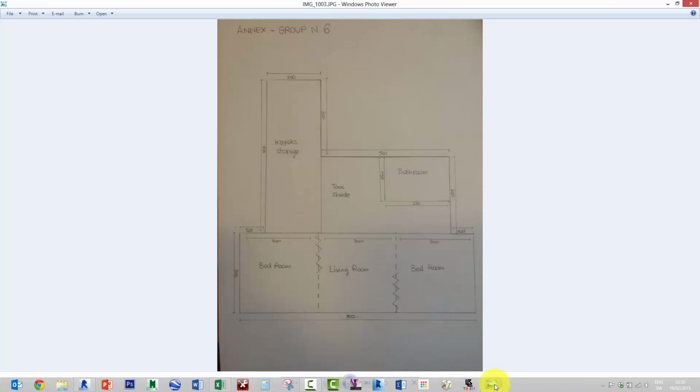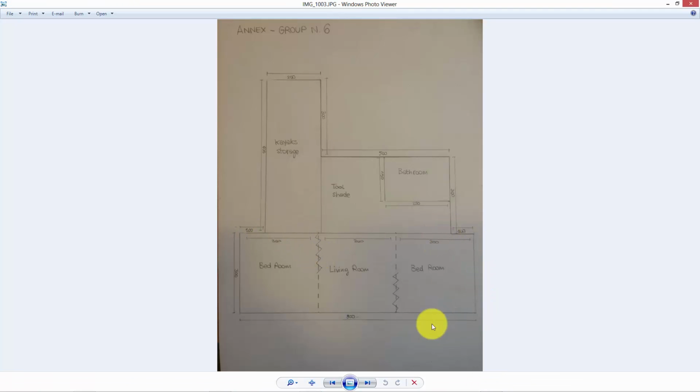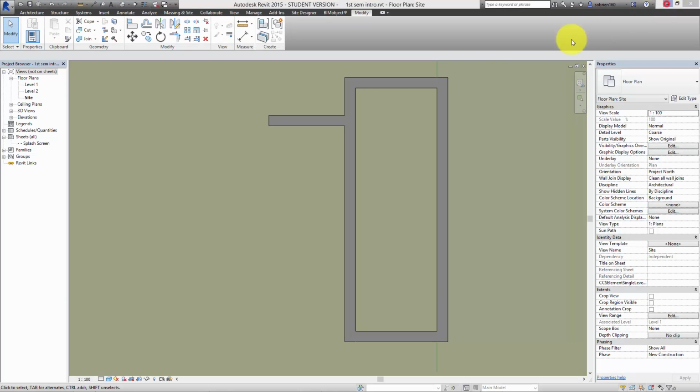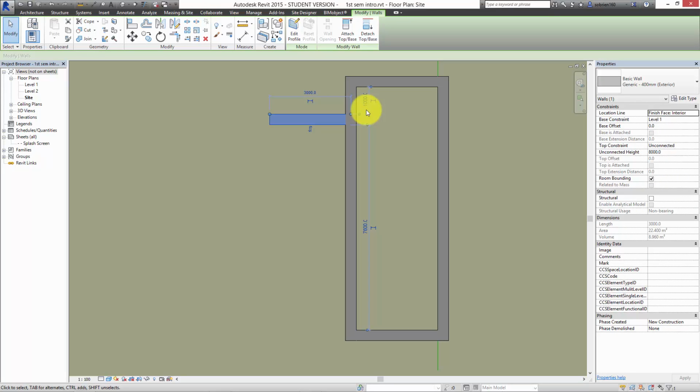So it's kind of the beginning point. I've drawn this box. Let's just rotate it. No, I can't rotate it. And now I've come in by 1,000 and I'm drawing in that direction. Okay. Since it's 1,000 on both sides, we can now mirror the wall we've just made and copy it over to the other side.